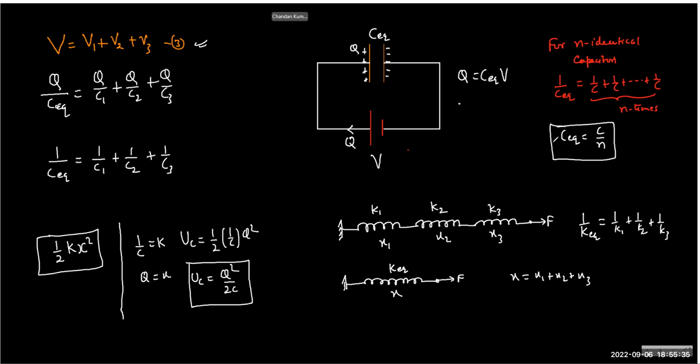Then you realize that you need 1.5. So 2 is more, 1 is less. To get 1.5, what will you do? There are many ways. You can take 20 in series, that will become 0.5, and then 3 such in parallel, it is 1.5.